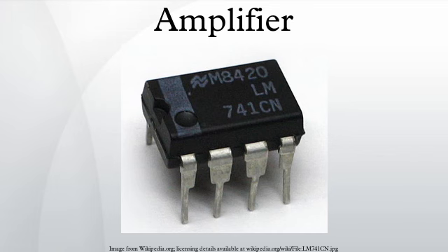A practical circuit using Class B elements is the push-pull stage, such as the very simplified complementary pair arrangement shown below. Here, complementary or quasi-complementary devices are each used for amplifying the opposite halves of the input signal, which is then recombined at the output.